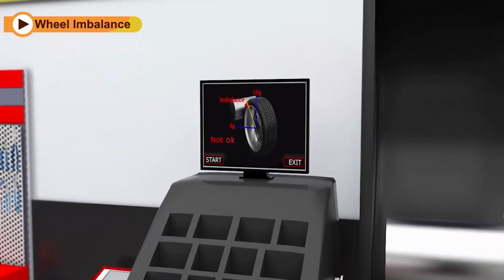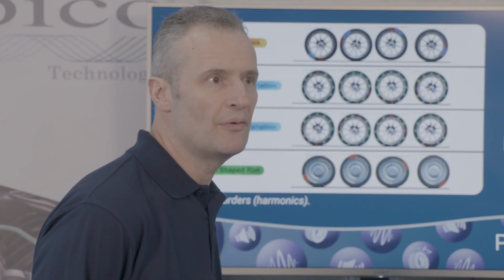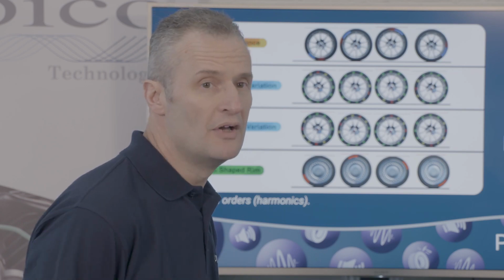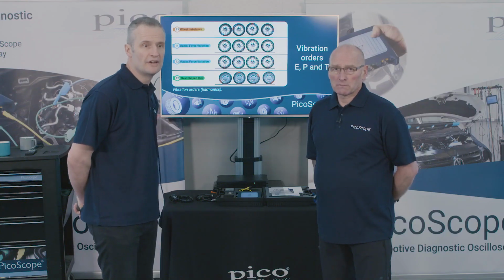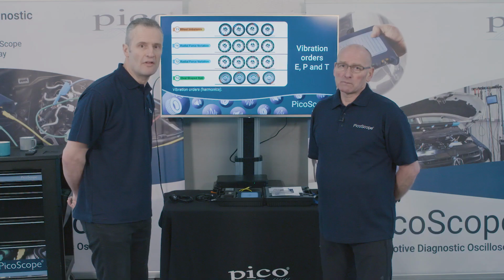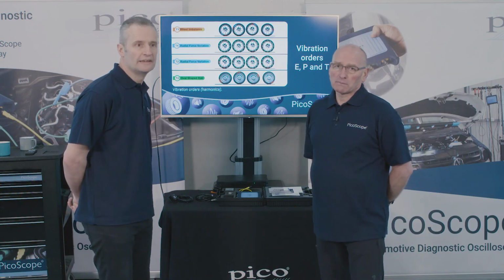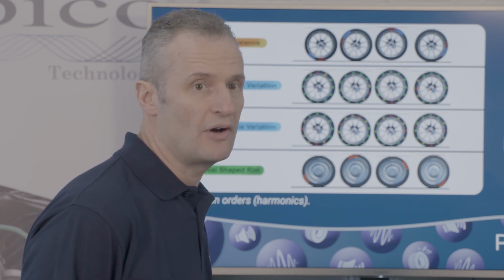The more high performance, the more rigid the chassis, the more sensitive suspension components become, the more radial force variation is visible and becomes a real issue. Without that style of wheel balancing, it's a real struggle to eliminate first, second, third order tyre vibrations. A certain must consider for low profile tyres.